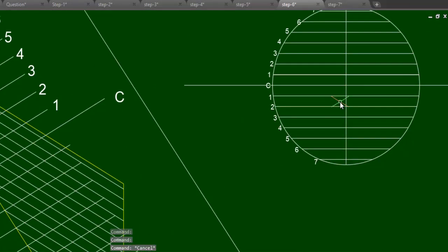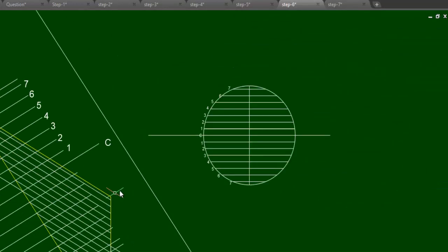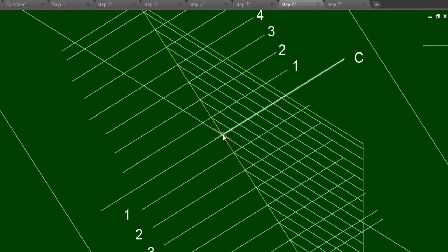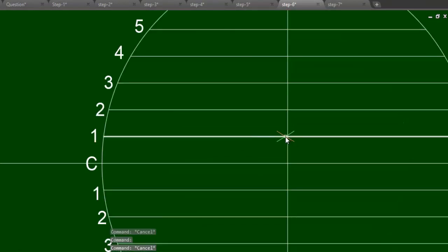That means you take the compass, and with the help of the compass you measure this distance from here to here. That compass radius you take, and that length you have to cut from this point on both the sides. Of course it will be 15 and 15 because it is a center line. So from this point you cut on both the sides. You will get 2 points here on this line, and go to the next line, line number 1, either this line or this line. Again you take the compass, keep the compass point here, and measure this distance. Either you measure left or right, it is the same. It is a circle only, it is the same.